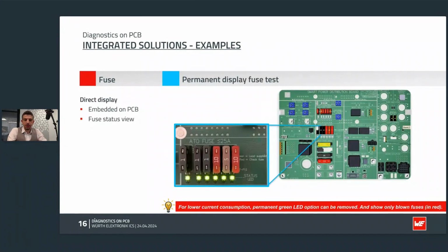Another solution will be to get rid of this button and simply connect the LEDs to ground. There is then always a power indicator on every fuse. When I say every, I mean, of course, the ones which are required to continuously show their status. This solution has a huge drawback. The current will be drawn in all cases, and if one LED is not much, the addition of many will have an impact on the global idle mode consumption.